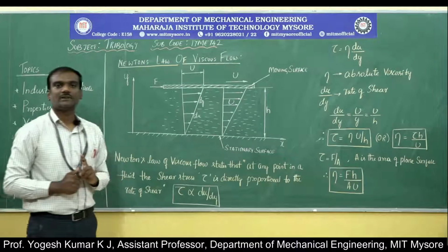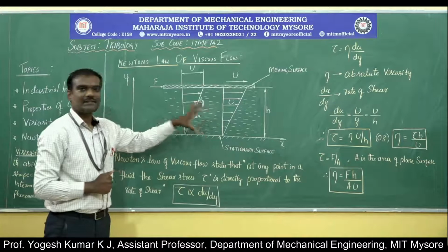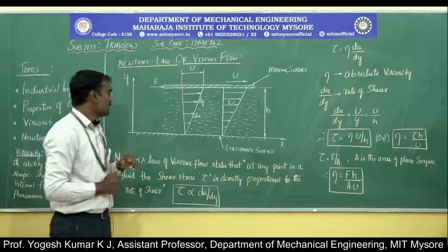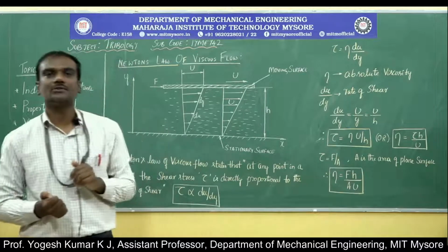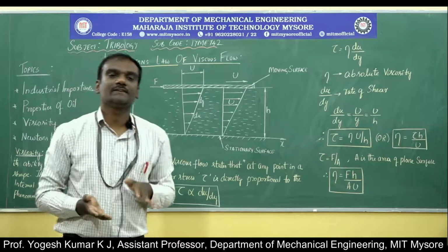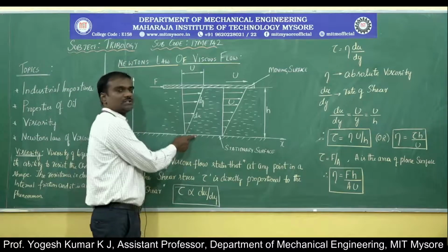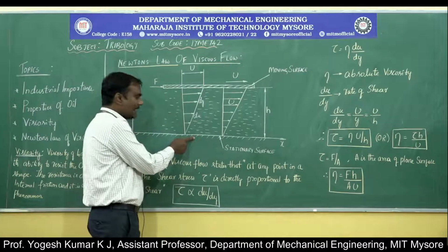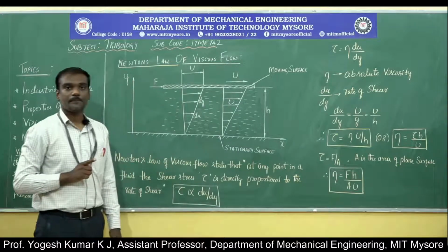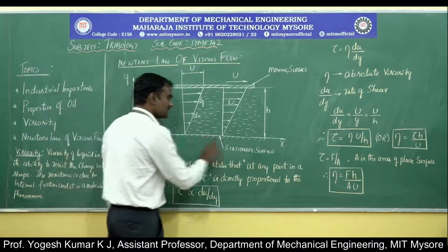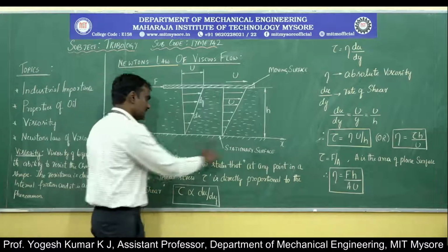That is the thickness of the fluid film, or the thickness of the lubricant, present between the two parallel plates. The lubricant between the plates gets adhered, bonded to the surfaces. The fluid very close to the stationary plate adheres to it, and its velocity is 0, because the stationary surface is at rest, a fixed plate.